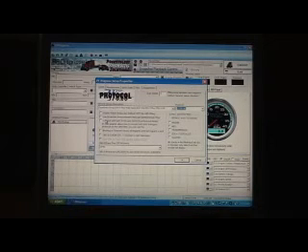If you have a Dearborn connecting with both J1708 and J1939, you may check this box. Connect with both J1708 and J1939 dual protocol mode. This section are filters. Normally, until you get used to the program, leave these boxes unchecked. If you check a box in here, you will be restricting PF-Diagnose to only operating on that particular module. So as a beginner, it's best to leave these unchecked. No other boxes should be checked at this time.